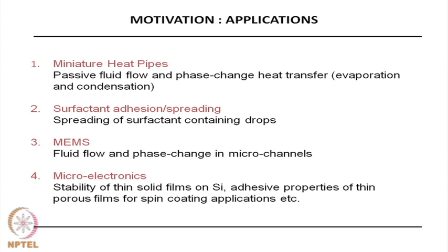If you would like to wet a surface with a liquid, and it does not do that on its own, the easiest way is to add some surfactant to the drop of liquid on the surface, which reduces the surface tension and forms a film ahead of the drop, thereby creating uniform coverage of the surface.